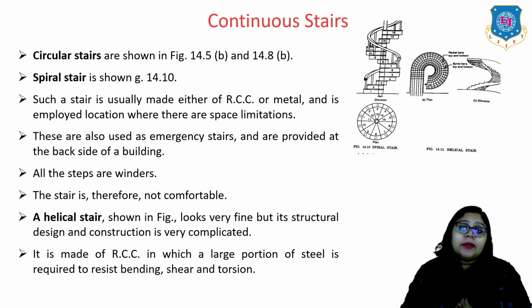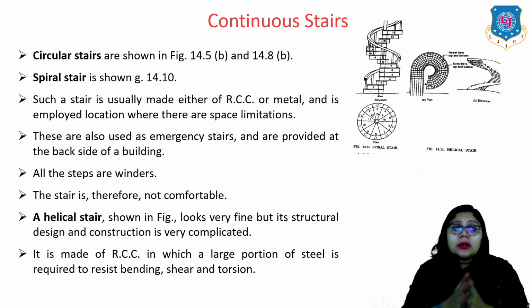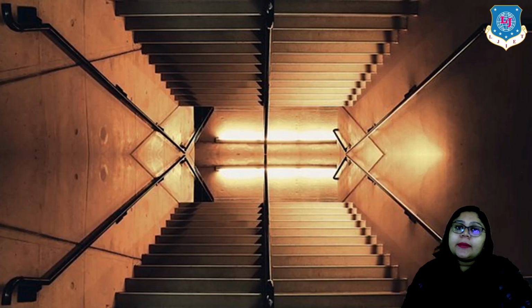Next is the helical one. Again, the figure of the helical stair is there, which looks very fine, but its structural design and construction is very complicated. It is made of RCC in which a large amount of steel is required to resist bending, shear and torsion. This is how the different types of continuous stairs are.